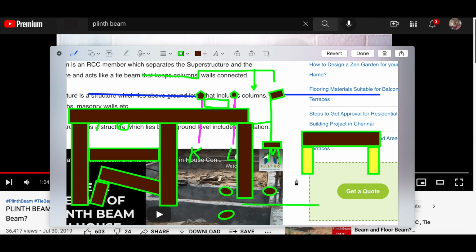That was not funny, but 11.10 to 11 inches. So this plinth beam, if you will, is now 11 inches. Either that, or they said this will be plinth, and this would be nothing here, and then this would be plinth. That doesn't make sense because they didn't do anything to resolve that rigidity here that would be needed. The lateral movement, and of course we see lateral movement in this failure.